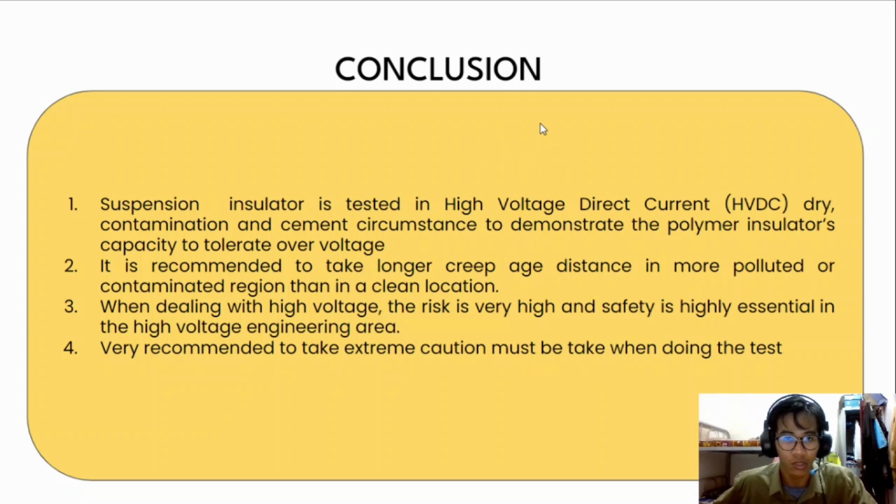Okay, today I will continue the presentation with the conclusion of our assignment. The suspension insulator is tested in high voltage direct current, dry, contamination, and cement circumstances to demonstrate the polymer insulator's capacity to tolerate over voltage. It is very much recommended to take a longer creepage distance in a more polluted or contaminated region than in a clean location, for example with water contamination.